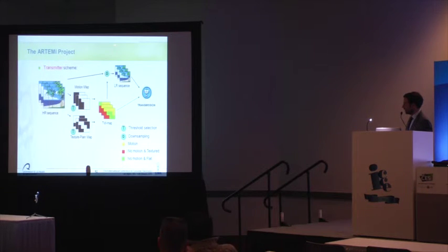We have in here the decimation process to pass to a low resolution sequence. In here we can lose the high frequency components, so before doing this we need to get texture information and motion information, composing a TM map, which means texture motion map. Okay, I'm going to explain how we proceeded to achieve this, because we need to have three different regions.